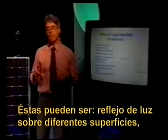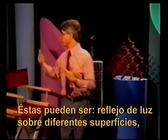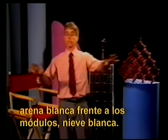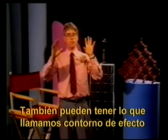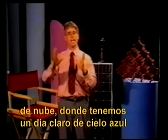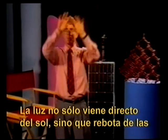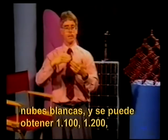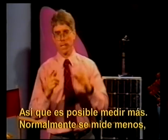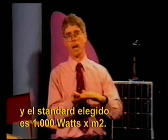What might those be? You can actually have light reflecting. You can have reflection off of bright surfaces, buildings, white sand in front of the modules, white snow. You can also have what's called edge of cloud effect, where you have a clear blue sky day and white billowy clouds. The light not only comes directly from the sun, but bounces off of the white clouds, and you can get 1,100, 1,200, 1,250 watts per square meter. So it is possible to measure more. Typically, you measure less, and the standard that's chosen is 1,000 watts per square meter.